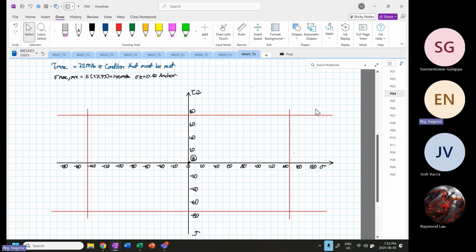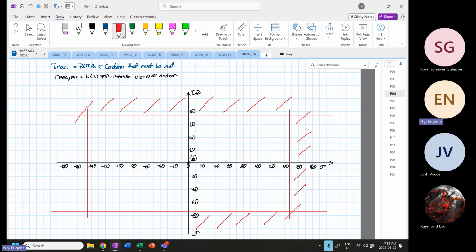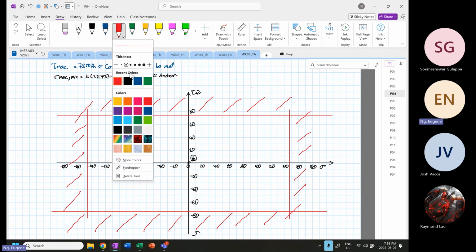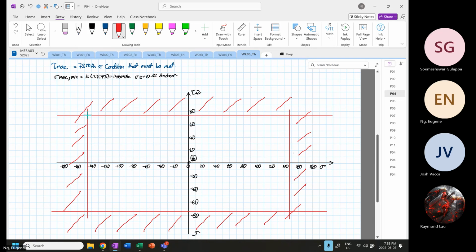So over here, this is our operating boundary. What do I mean by that? The 3D Mohr circle cannot touch anywhere that I'm shading now, outside the red box. So I'll draw a thicker red box for you. It cannot touch this red box. If it touches or goes beyond the red box, the material will fail.